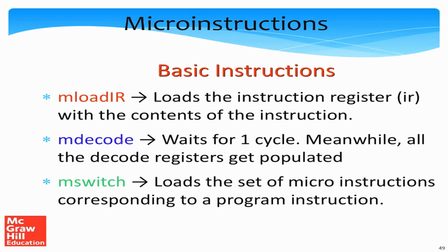Alright, so let's introduce some basic instructions. We don't want to introduce many, but let's at least introduce as many as are required. So the basic micro instructions are, let's make a convention that we'll start all micro instructions with the letter M. So let's look at M load IR. M load IR loads the instruction register IR with the contents of the instruction. So whatever are the contents of the instruction, they come from the instruction memory and get stored in the instruction register IR.